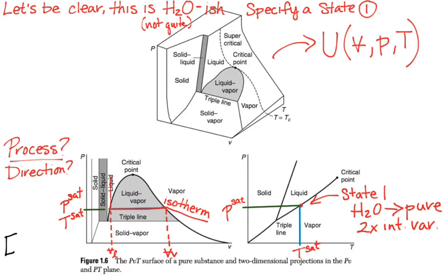The process, right, at any vapor-liquid equilibrium state, if we were going from left to right, would be evaporation. I'm going from a saturated liquid where there's effectively 100% liquid, just on the edge, about to boil, at 100 degrees Celsius, let's say, at atmospheric pressure, just at that threshold of boiling, but no vapor. And then as we go from left to right, we have an increasing quantity of vapor in the system. So the phase is changing from liquid to vapor.